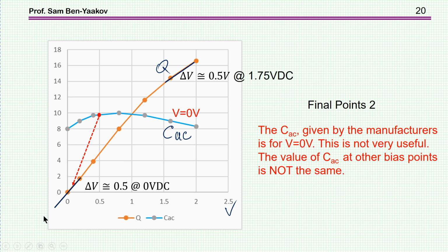But that's not where you'd like to work, because seldom you'll use these capacitors with a signal around 0. This may be only in, say, resonant converters, but certainly not in PWM converters or DC coupling cases. So this curve is really not very useful.